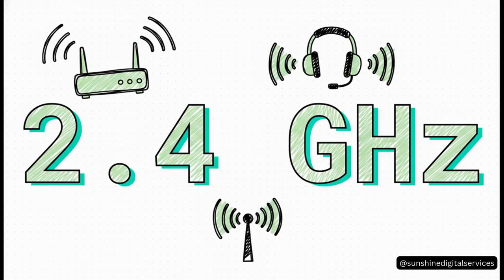Now, it's super important to remember that antennas are designed for very specific frequencies. The dimensions of our patch antenna were carefully chosen to work at 2.4 gigahertz. And that's no accident. That's the frequency band used by tons of devices, like Wi-Fi and Bluetooth. So we're specifically testing to see if it performs well right there.